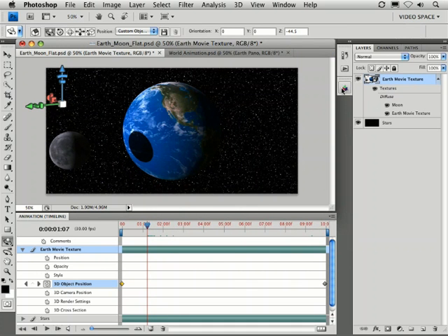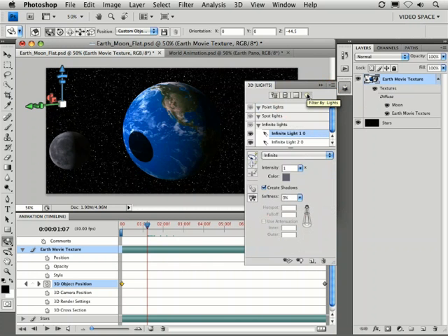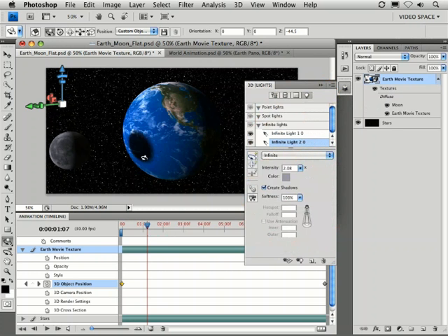If I go back in here to my 3D scene panel and select this icon for filter by lights right there, I can actually go down here, target the light that I want to soften right here. Then I'm going to go down here and select softness. Clicking and holding on this, I can then move my scrubby slider over to the right, and we wait for a moment, and there it is. It's now softening the edge of that shadow, very similar to the way the moon's edge would be softened through the Earth's atmosphere. Fantastic. So now we've set up that quality.